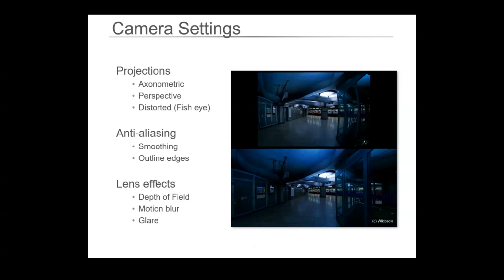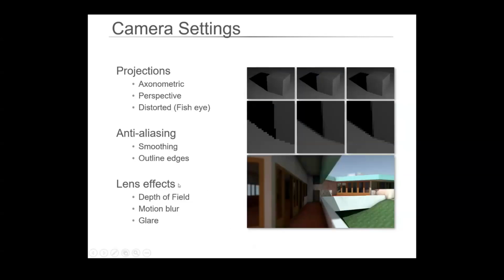So it's always a good way to experiment with those sorts of things and see what works for you. Some of those angles, you'll find that you place the building there and it just looks bland. It doesn't give it much oomph. But then when you change the view angles and bring yourself, say, closer, you get a lot better feel for the building. And then you can introduce things like depth of field and motion blur, glare, so we can then start producing these really smart images.